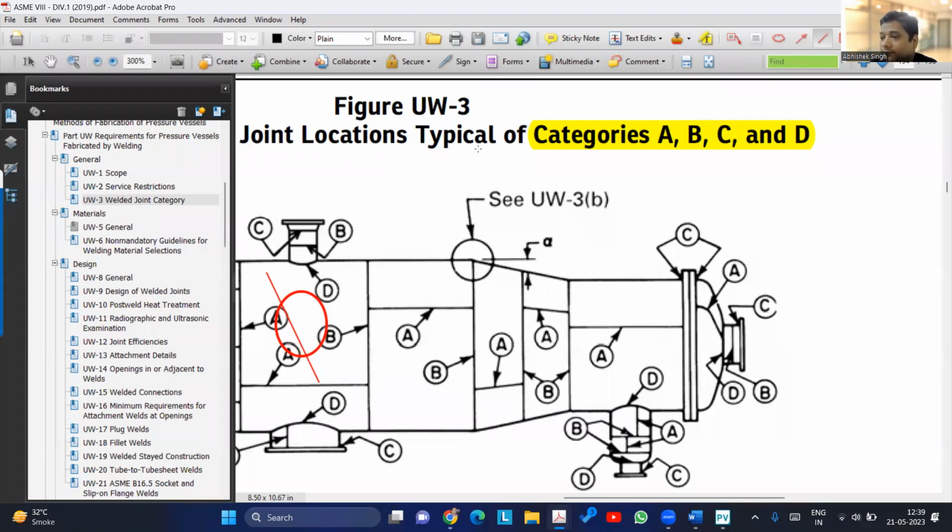and the shell is connected to the body flange, then is it a B joint or C joint? That is a C joint. That is also a C joint. This is nothing but a flange only, no? This is a body flange. And if you are making a butt weld, then you need to have a lip. So that portion will look exactly like B, but we'll have to see why there are different PTC requirements.